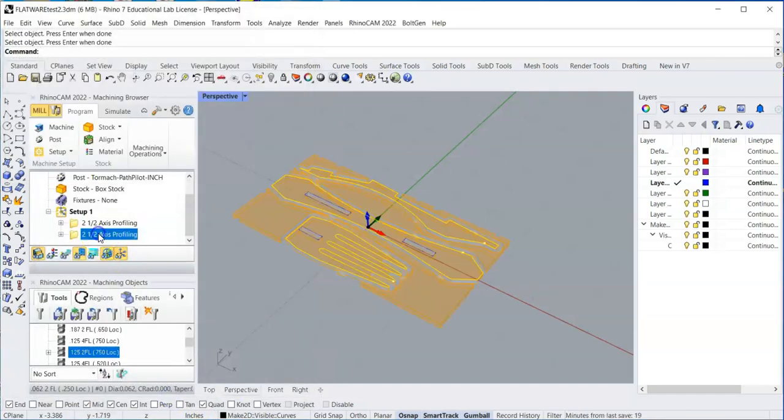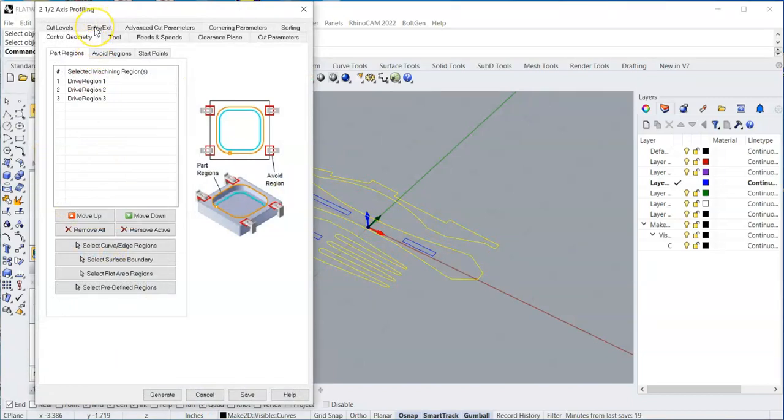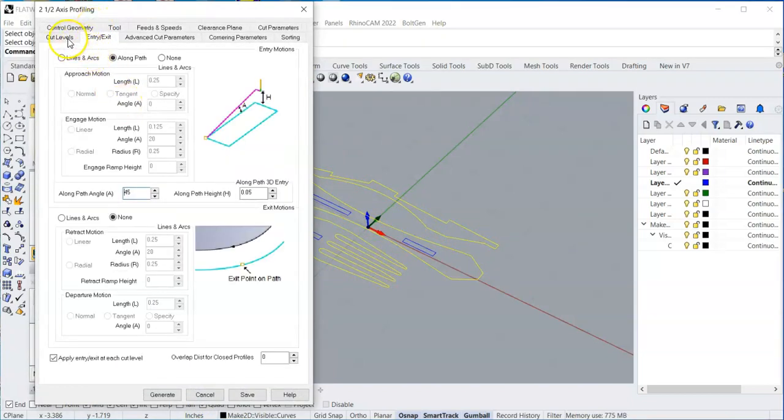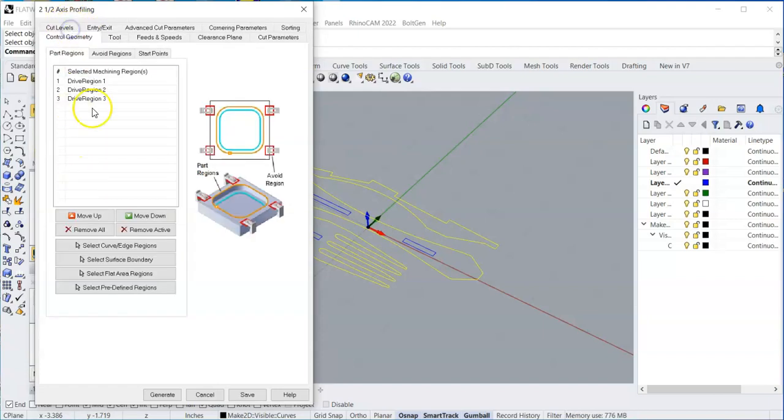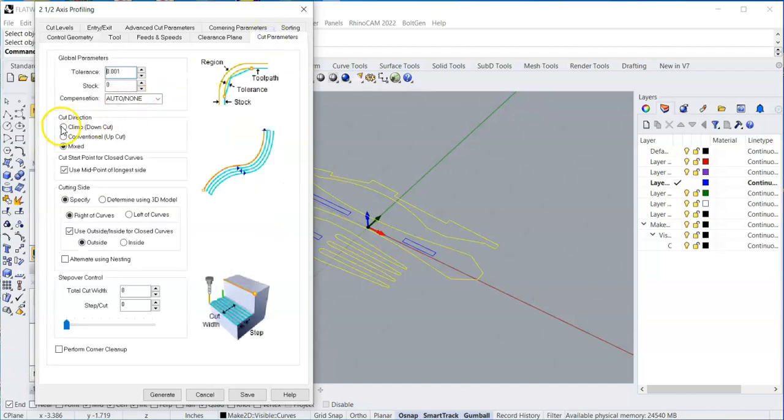Different materials work better. Like let's say we're cutting acrylic. We might actually go conventional with acrylic or wood if we're worried about chip out, or if we're worried about friction. You might actually mess with that a little bit and change that depending on what material you're cutting. And again, there's a lot of science behind that I'm not going to get into.